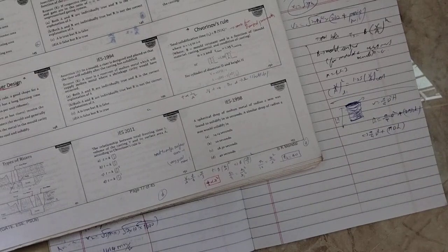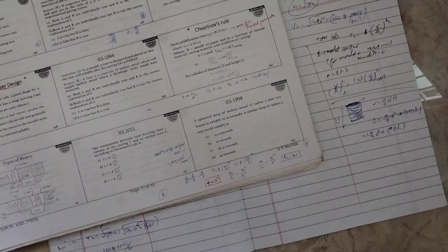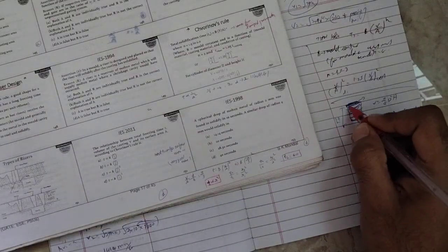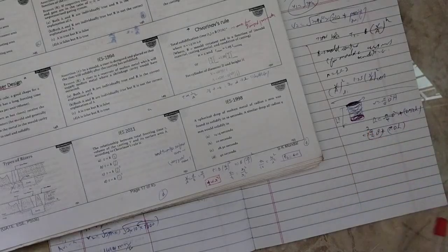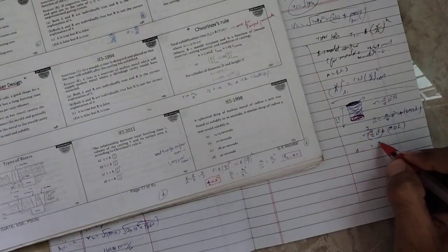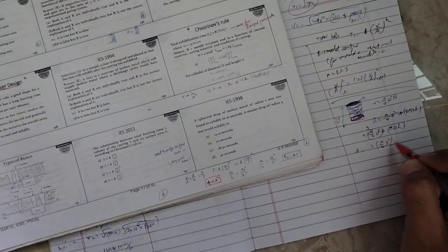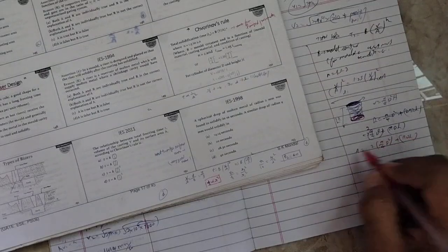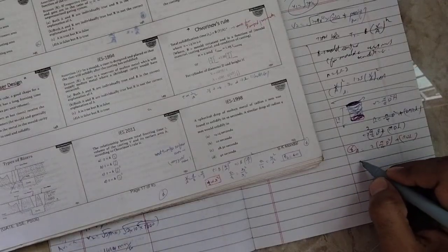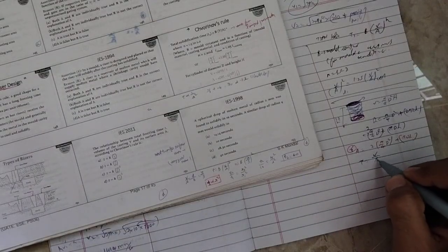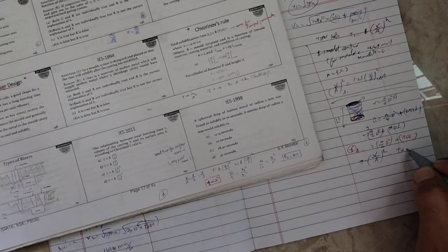Okay, so the next thing is this. We are just considering one area, but what about this one? So we need to multiply by 2. The entire area is 2 times pi by 4 d square plus pi d L. Here each and everything we need to consider, guys. Do not forget. So the next thing you can see: time equals (V by area) the whole square. Here time is directly proportional to the volume and inversely proportional to the area.